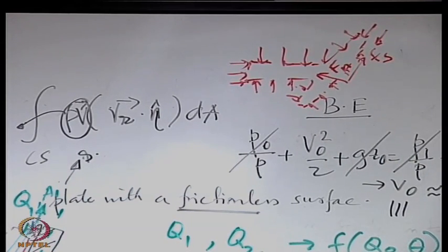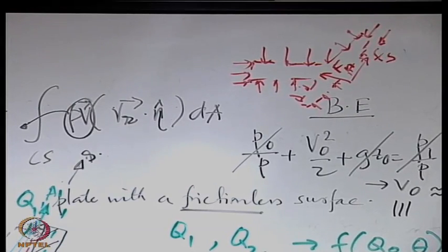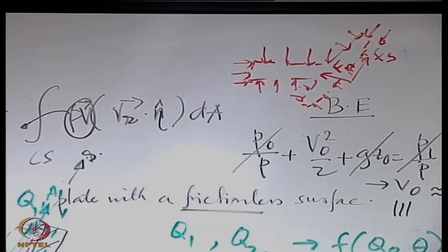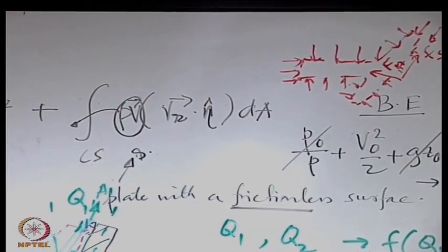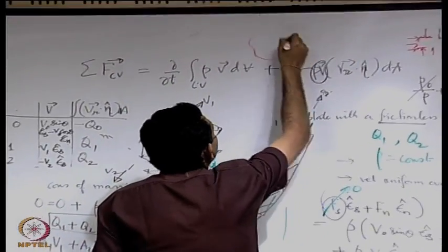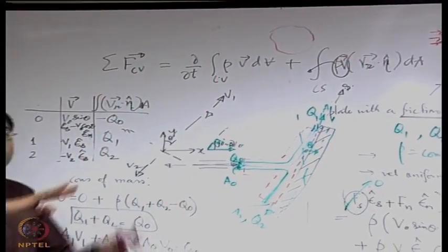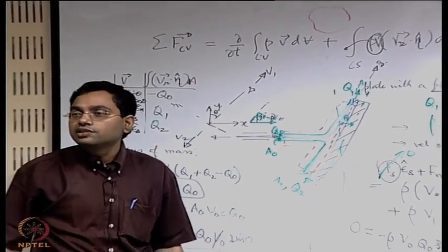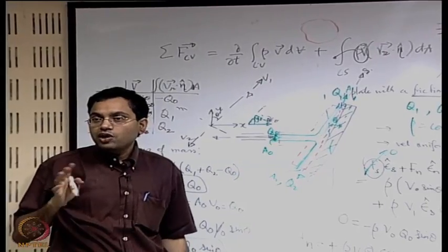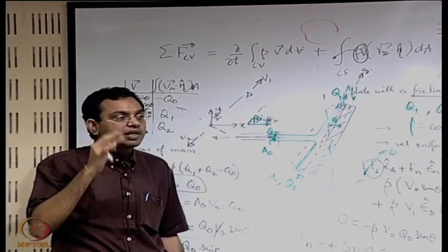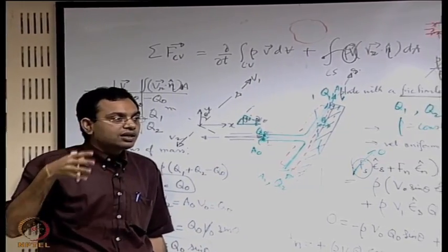Have we considered the contribution of this? We have not considered it, but magically we are expecting that it is giving us the correct information on forces. This magical thing is possible because if you have a closed contour over which you have a uniform pressure distribution, then irrespective of the shape of the contour the resultant force is 0, because of a very special nature: pressure locally is always normal to the direction of the surface.